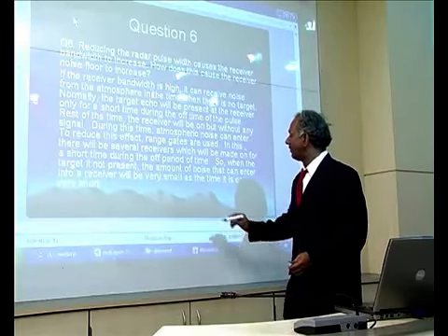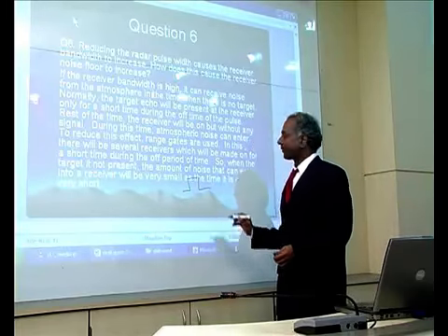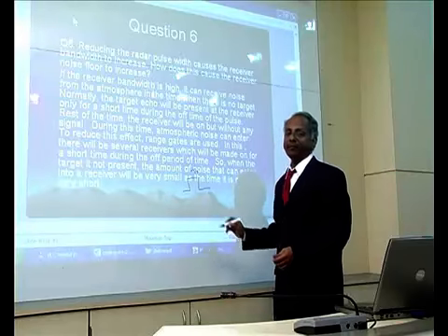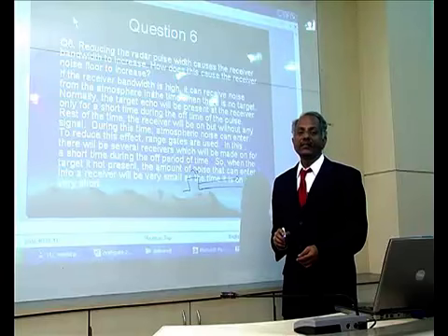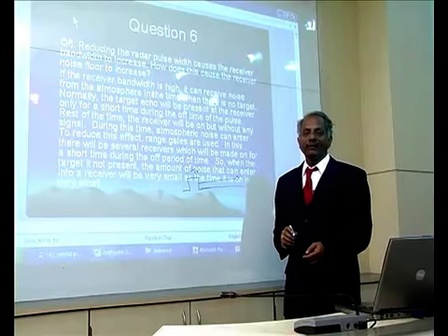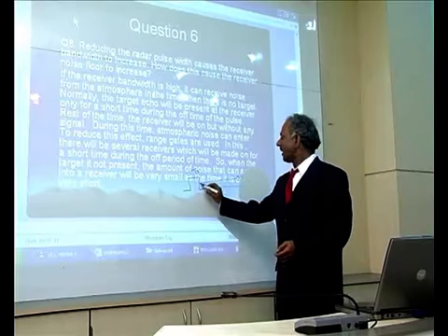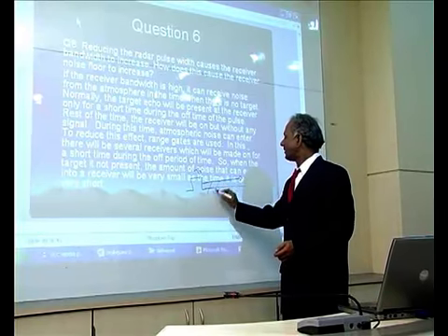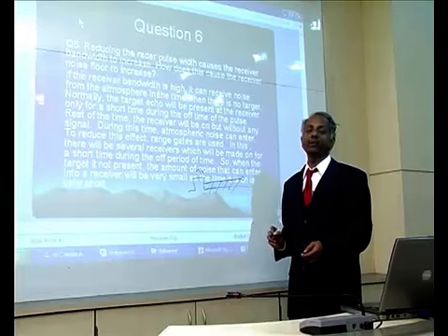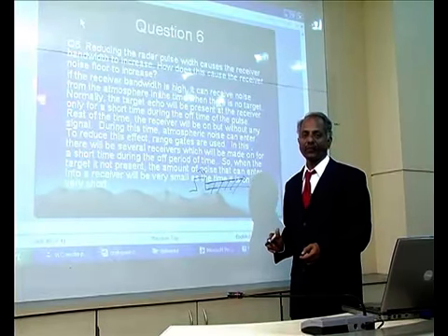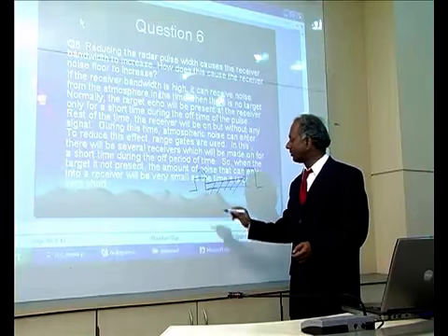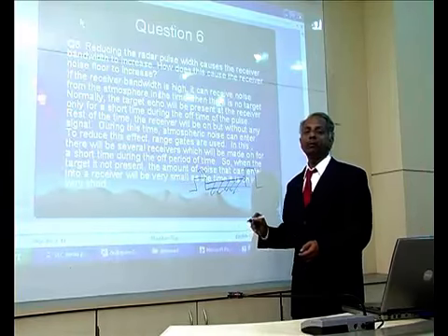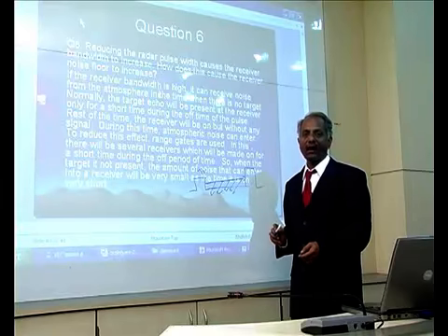Here we have a pulse being transmitted during the transmitting time, and the receiver is on to see the echo from the target. So the receiver is open to receive any signal, whether it is from the target or from the atmosphere. So if the receiver bandwidth is high, it is going to attract a good amount of noise from the atmosphere, or the noise floor is going to increase.